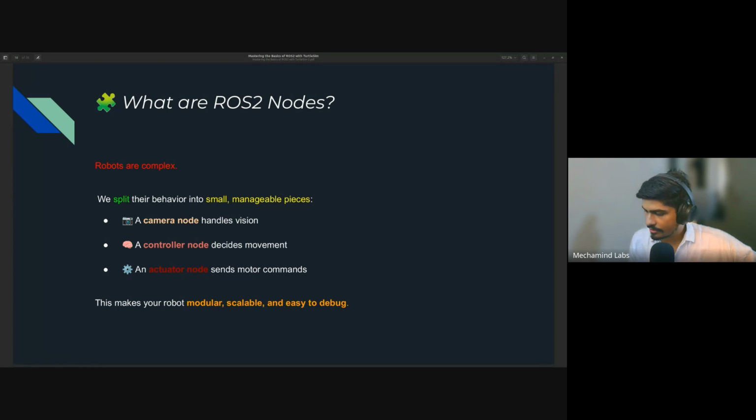You can run ROS on your laptop or PC or Raspberry Pi. You cannot run it directly on ESP32; you have to run micro-ROS on ESP32. We will not be going into micro-ROS because most of you are beginners, and we will cover it some other time. Yes, you can use STM32 as well, but I'm not sure micro-ROS will run on it or not. Okay, so this was about nodes.